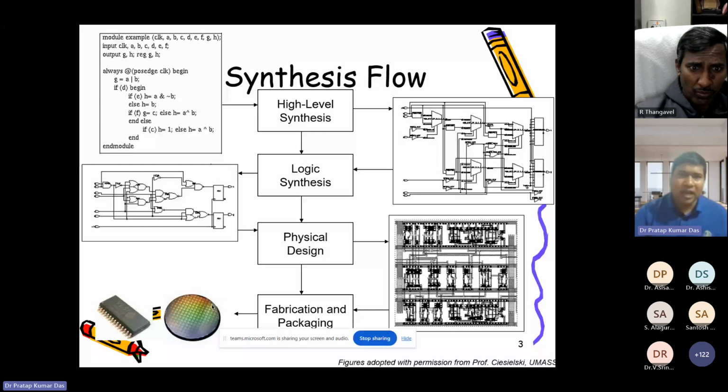Now we have a high level logic, right? From there we need to convert it to GDS. How does that get converted? That is through this physical design. So basically from these gates, it has to come to this lower level, transistor level, layout level design. Okay, now let's go to what we mean by the physical design.